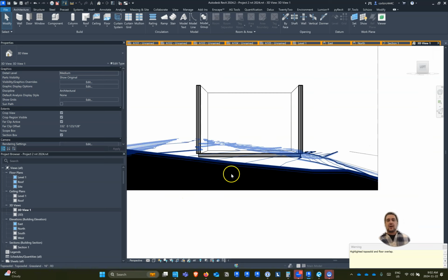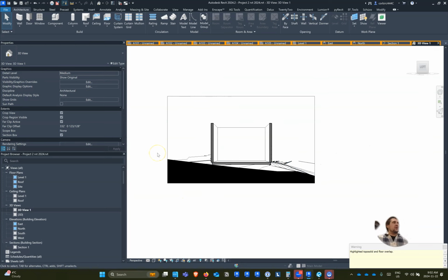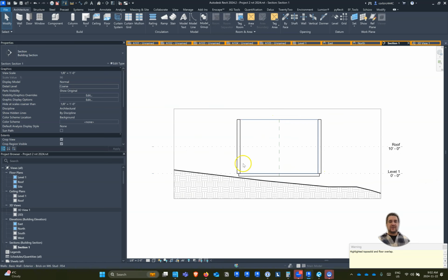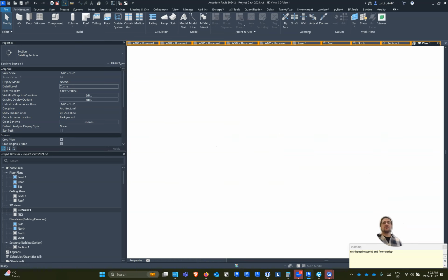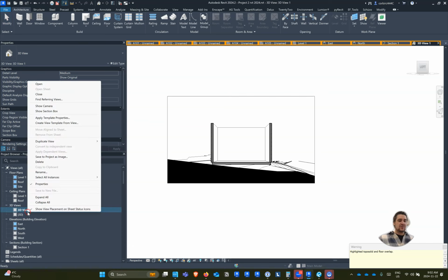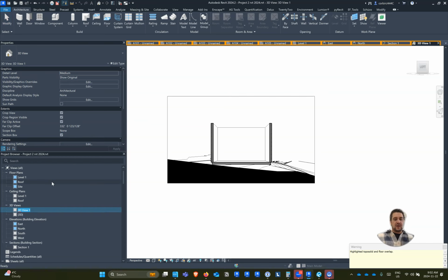And you can see this view, we don't have our level lines going across because it is a camera view, it's a perspective view. But in our actual section, we would have those level lines going across. And so you could apply those same things. I think for sections, it's better to just show this perspective section. So we could just rename this as 3D section 1. But I think these views communicate a little bit better, so I tend to recommend showing these over just a traditional section because they look better.